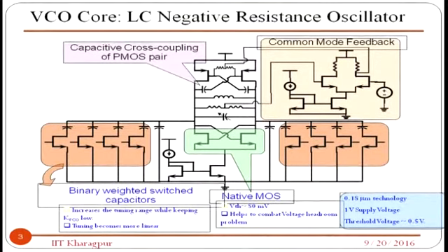You have one resistance. You want the voltage to be the same on both sides, so you have two resistances, the same resistance. From the middle of these resistances, you take the node and put it into a differential pair, and remember that, the output of that goes to the two resistances, and one is feeding this gate and another is feeding this gate. You have to remember that to have a symmetric swing, the voltage should be the same on both sides.